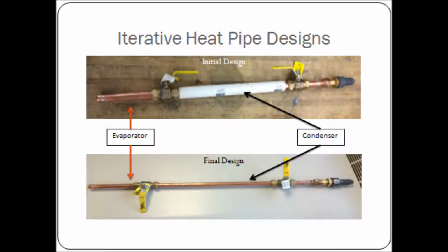Once the vacuum has created a low pressure in the condenser chamber, the second ball valve can be closed. Once the first valve is opened again, the working fluid will be exposed to a low pressure environment, which is critical to the operation of the heat pipe. This low pressure environment will lower the boiling temperature of the working fluid within the pipe, making the heat pipe effective for a more applicable range of temperatures.